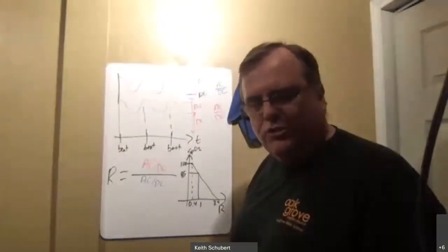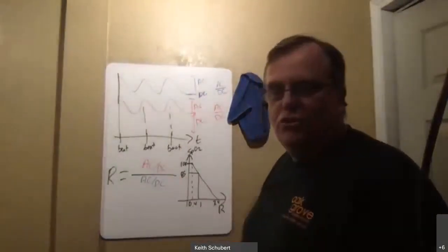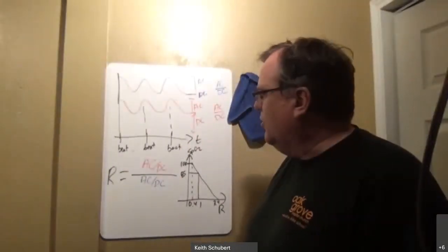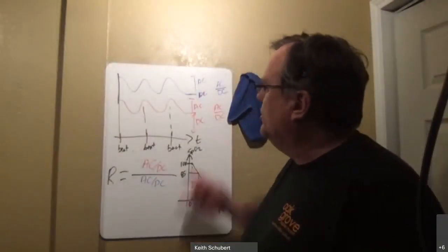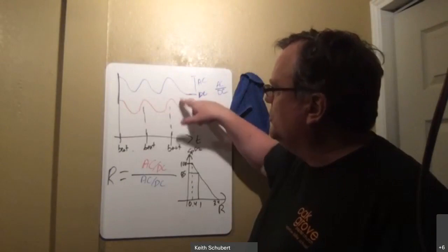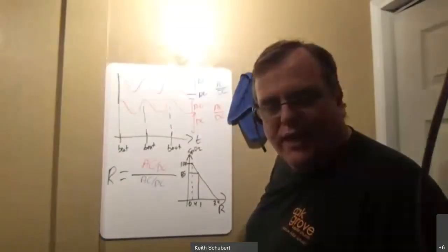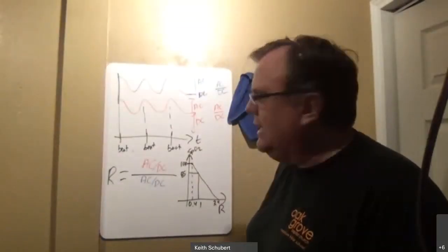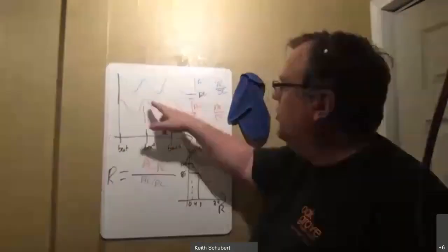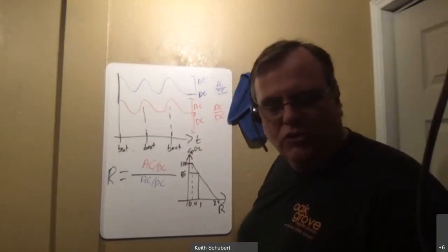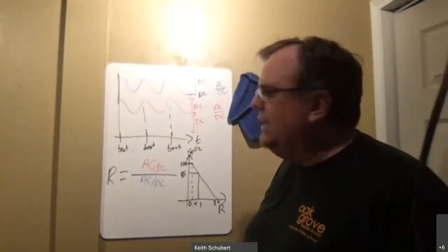We've now removed all the tissue effects. We removed huge amounts of our problems by doing this time measurement. So we have to do a decent number of measurements. It'll take at least a second or so, because we have to calculate an average between these pulses, or at least peak and min. So you need at least one heartbeat to be able to do that.